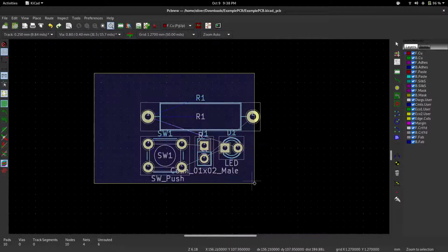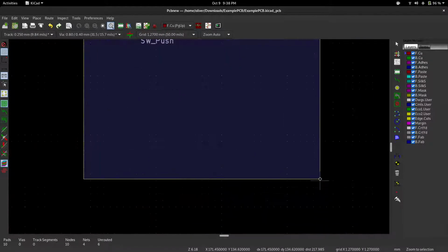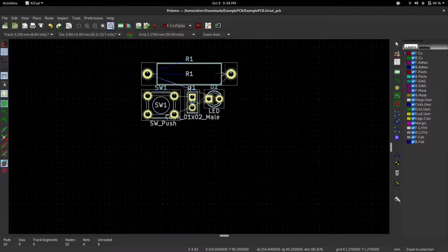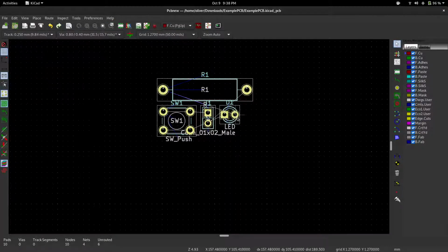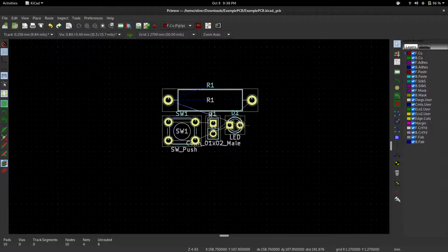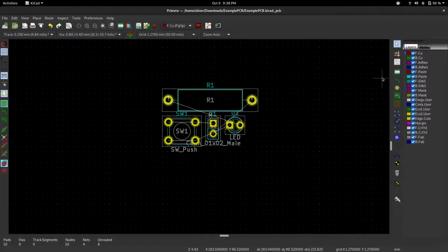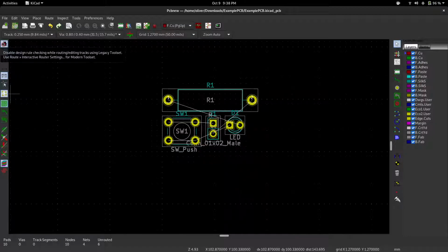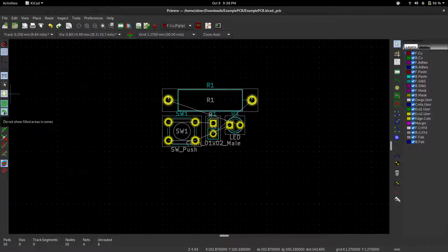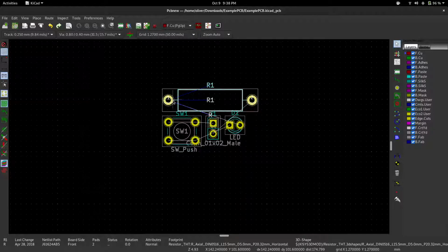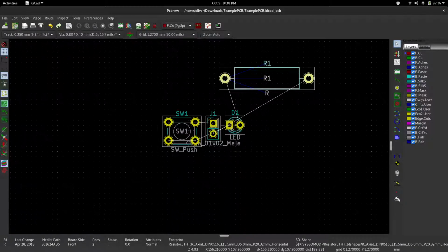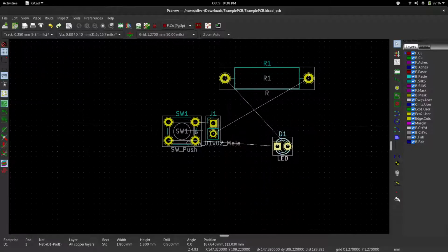So I just zoomed in a whole bunch. I'm going to zoom in a whole bunch more. Okay, or actually, sorry, zoom out. So you notice that it doesn't do any electrical connections automatically, but it does have these white lines called rat lines, and that's the electrical connection. So if we start moving things around, hang on, how do you... Oh, you can press G to grab something and move it, I believe, but something's wrong here. It's like selecting all of them. Give me a second. There we go. Yeah, there you go. Okay, you just drag. So you click and then drag to move stuff.